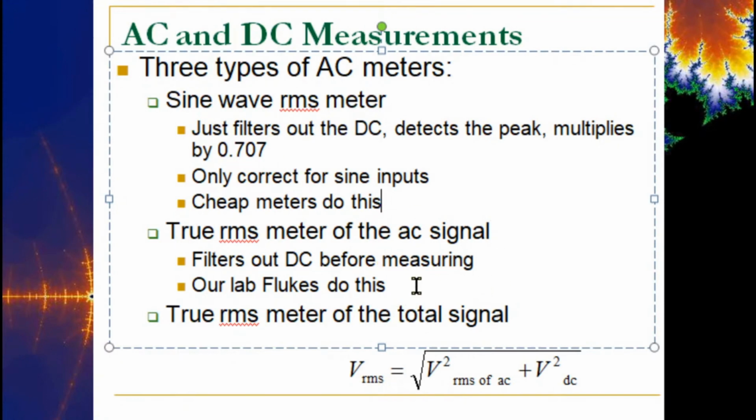If we were in the lab right now, we actually have bench Flukes, the Fluke 45, which is a 4.5-digit multimeter, and it's auto ranging. It's got all these niceties on it, and it is also true RMS. But brand new, those things are upwards of $1,000, okay? So when it comes to electronic measurement, you absolutely get what you pay for.